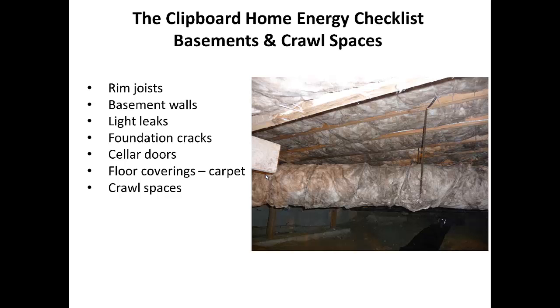And in crawl spaces, you want to make sure that you've got insulation in those areas, because down there is an unconditioned area. And one caution is that if you've got plumbing pipes running through here that have never frozen over time, and let's say this is not insulated, but you've never had any problem with freezing pipes or anything like that, now you're going to insulate. And if you've got a pipe running through here, what you've done by insulating is you've taken that pipe that was relying on the heat coming from up above to keep it from freezing, and now you've reduced that water pipe that's run down through here to not be able to be warm anymore. And so it's going to freeze, and you're going to have a broken pipe.